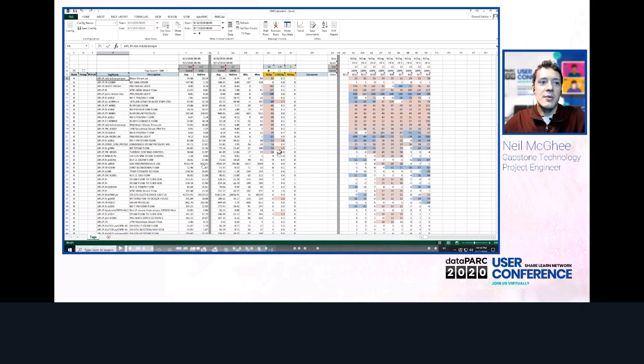Even after we have performed all this tag filtering, we still have some values near the top that we'd prefer to be sorted out automatically. Many tags are correlated in ways that are obvious, with some level of process knowledge, and are not likely to be the root cause of issues that we see. What we really want to know is which tags have changed in unexpected ways. We can achieve this by creating a PCA model based on our baseline period. A PCA model is a linear model that maximizes variance with the fewest variables.